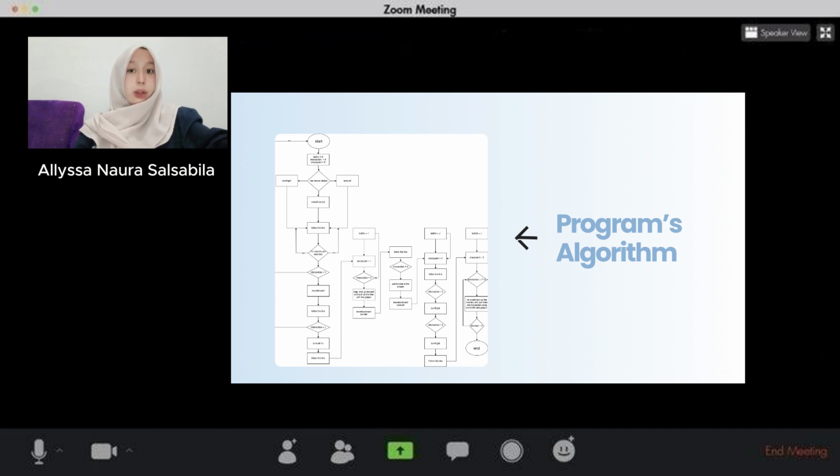If all 5 sensors are detected, it will count as intersection 1, and it will move forward and follow the line. And if all the 5 sensors are detected again, it will count as intersection 2, turn left for 1 second and follow the line, known as checkpoint 1. After that, if all the sensors are detected again, it will count as intersection 3, which will go forward and pick up the tree with the gripper and forklift, move backward and follow the line.